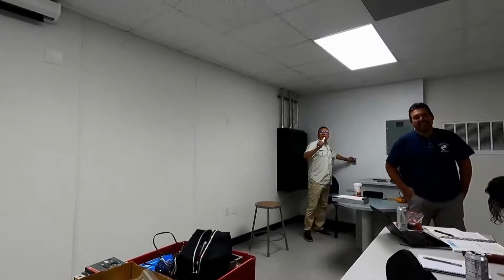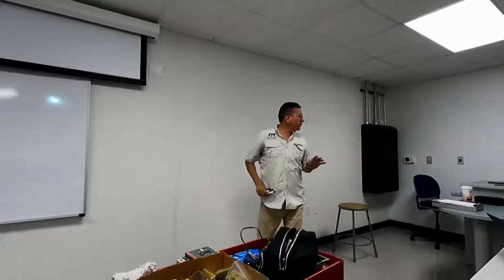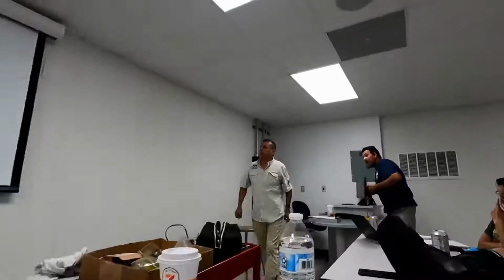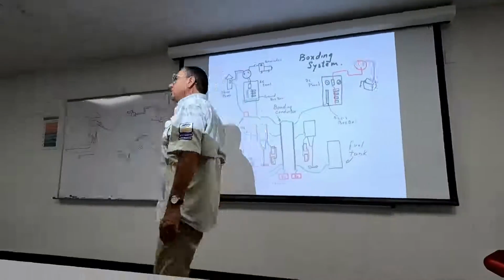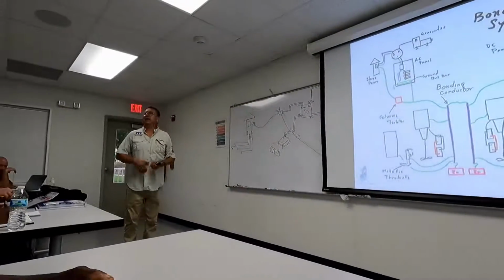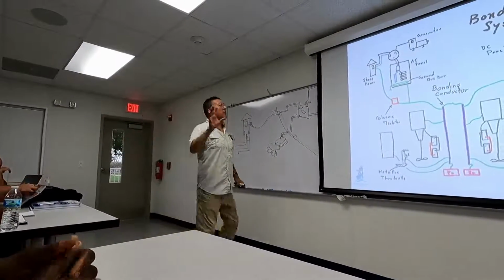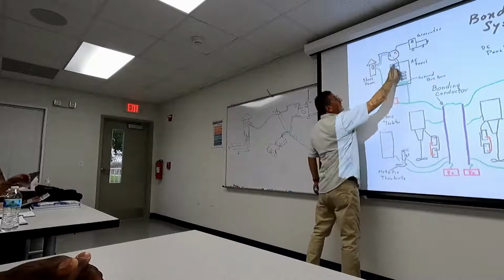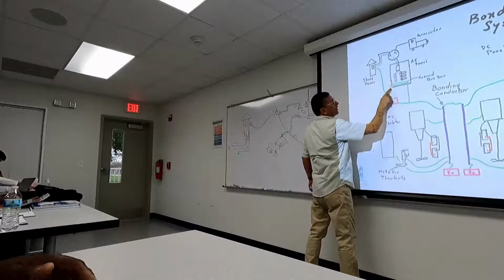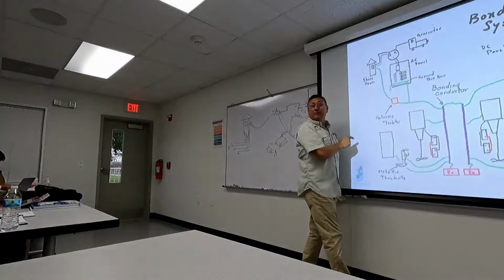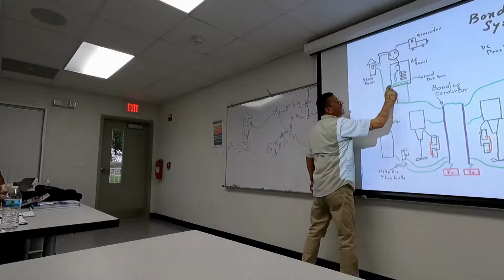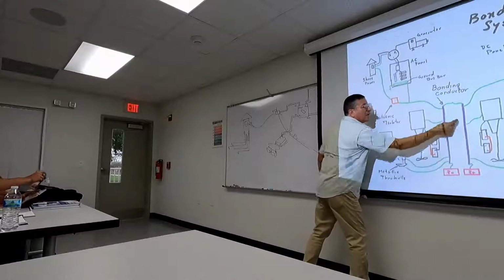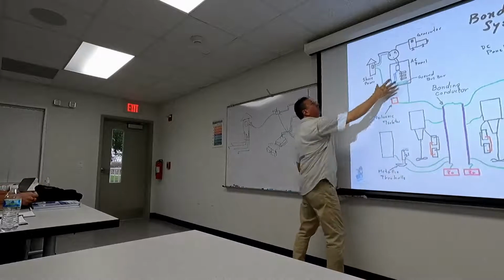Guys, only to refresh quickly the topic about the bonding. Pay attention. This is a boat with the AC panel and DC panel. Follow me. Shore power, generator, the switch selector, you remember? Main breaker, small breakers, neutral bus bar, negative, ground AC panel, AC bus bar, and the ground AC bus bar enter into the bonding conductor. This is the AC panel.